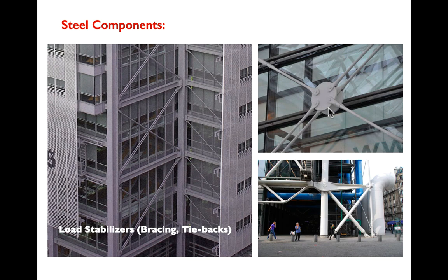And this speaks a little bit to the versatility of the material. We've got basically cables here. We have cast turnbuckles there. Probably rolled cylinders here. And then the actual plate looks to be cut out of a solid plate of steel and then drilled to provide access for the pins.